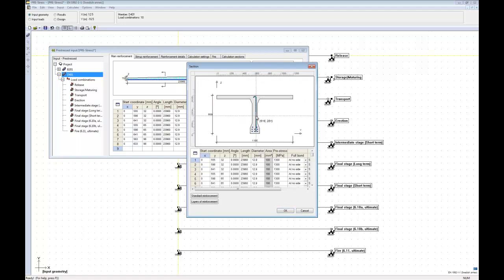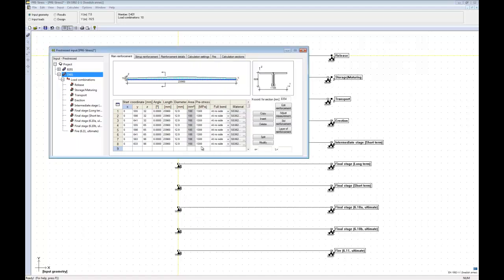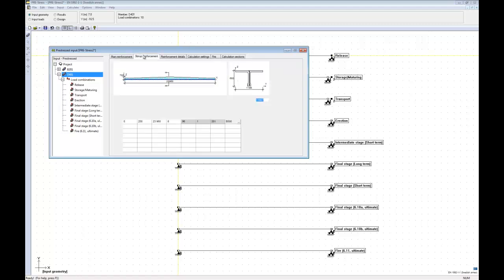This is only one leg of the stirrup that goes down here. The web is usually quite thin here, so it's not possible to have several legs per stirrup in the cross-section plane, but it is possible to have it alongside the other.